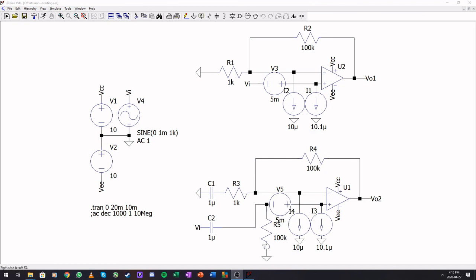You need to add the resistor for the DC bias countering, and you need to add an additional capacitor on the input so that no DC voltages can come in and affect any of our circuitry on the input side. And remember that this ground path here is extremely important to maintain, or else this amplifier will not be biased. So you cannot have this capacitor here on the non-inverting configuration without having the resistor.